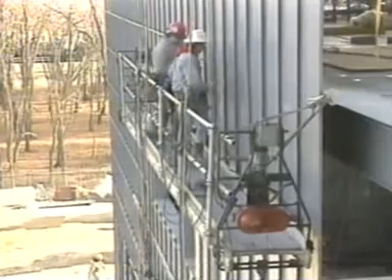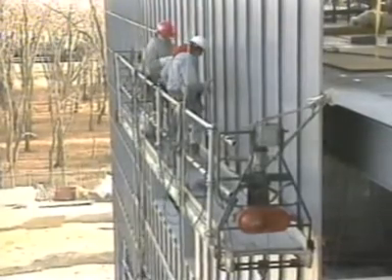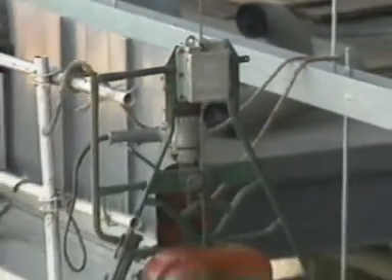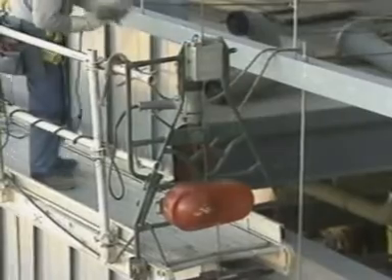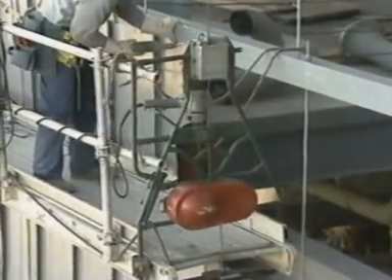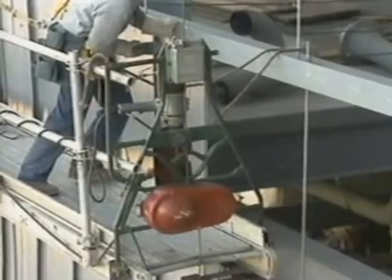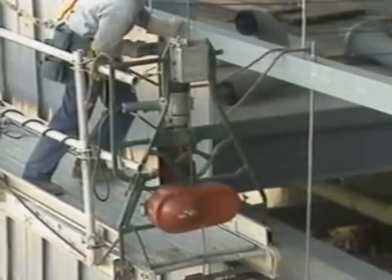To ensure true winding, at least 3 turns of rope should be left on the hoisting drum when the scaffold is at its lowest position. This also reduces the force exerted on the rope at the point where it connects to the drum, and lessens the possibility of the rope slipping from the drum or breaking.